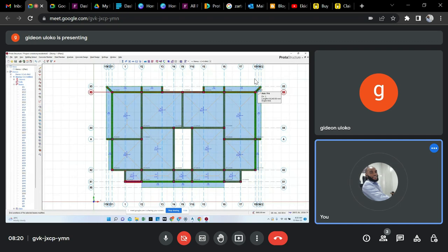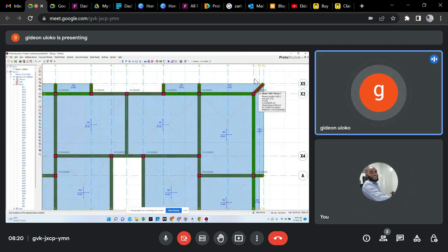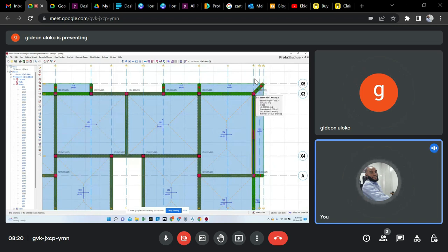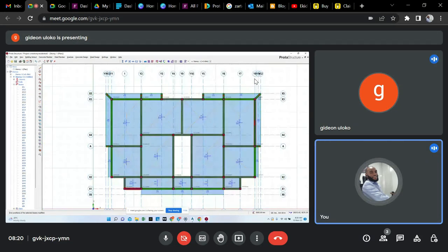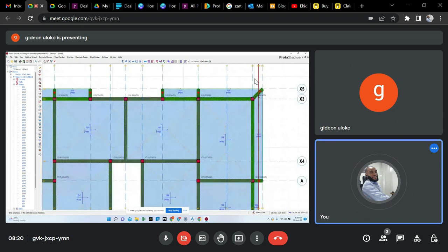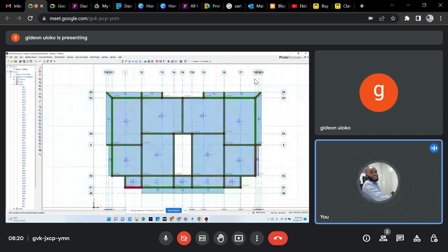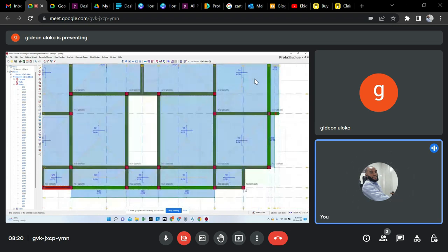I end. And these ones are going to hinge I, right? No. Those ones are cantilevers, so you don't hinge that one. You don't hinge cantilever ends, cantilever beams. Leave them as their cantilevers. Don't hinge them because they are meant to be fixed. Okay, I end, not J.